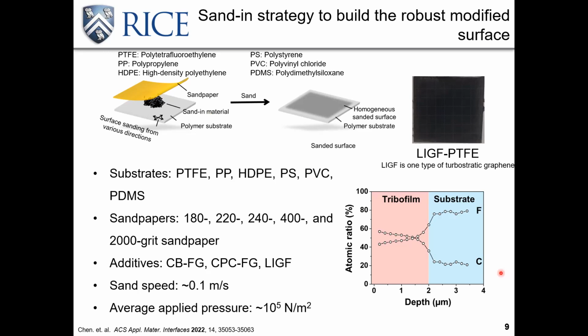So you're saying it would be good to put a substrate to support the textile, and then do the sandpaper on it. Yeah, because when you apply force to your material, you need to put something at the backside. Otherwise, if your material is soft, it will deform and cause an inhomogeneous coating, which might not be good for your application. We want a more homogeneous coating, right? So that's why I think using a very flat surface at the backside to support it can make sure you get a homogeneous coating.